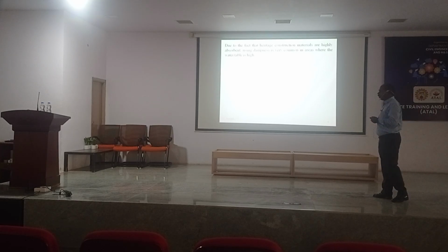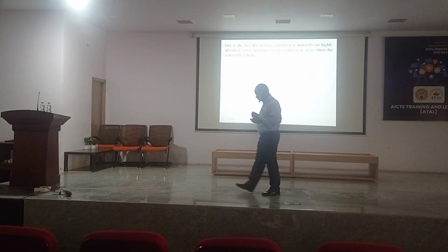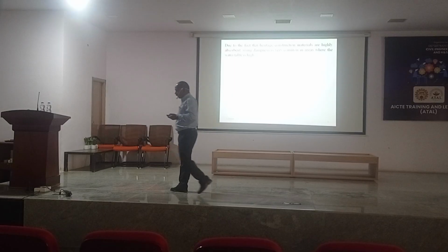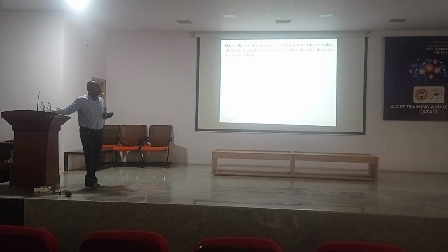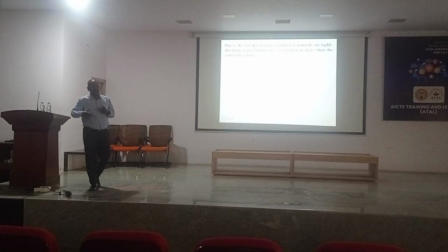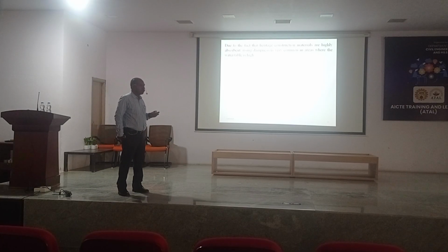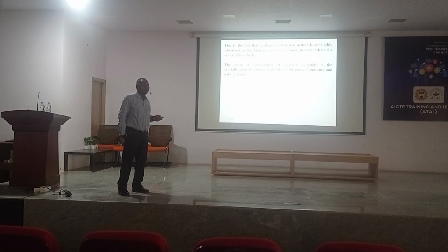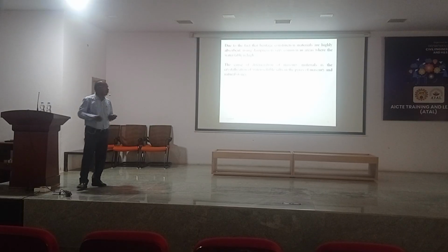Right. The repair materials are very absorbent. That means they will absorb moisture. Our existing mortars are old mortar, therefore they can absorb the moisture. The mortar may be decayed, and rising dampness is very common in areas where the water table is very high. In coastal areas you can observe that. And water also creates problems. This is the major problem in many areas, especially in European countries.